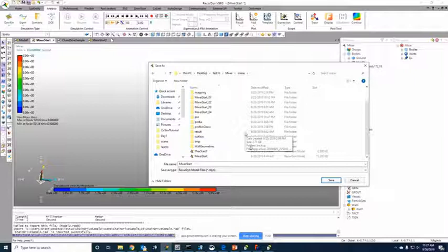And then that's where you place a copy of your RecurDyn model file, or RDYN file. It'll happen naturally. You start out with your RecurDyn model, then you start with your Particleworks model, and as soon as you save the Particleworks model in this co-simulation folder, the scene subfolder will be created for you.